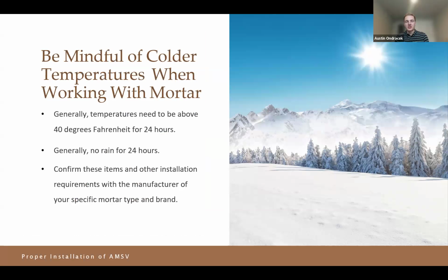And then I've mentioned this too, but just be mindful of the time of season, the time of day that it's being installed. If it's a colder afternoon or a colder day, a mortar's not going to cure as much. You generally need it to be about 40 degrees or greater. You don't want to have it rain for about 24 hours.